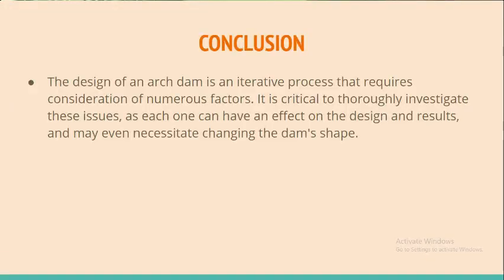So we will move to the conclusion. The design of an arch dam is an iterative process that requires consideration of numerous factors, such as topography, geological and foundation conditions, and volume change of the ground due to climate conditions.